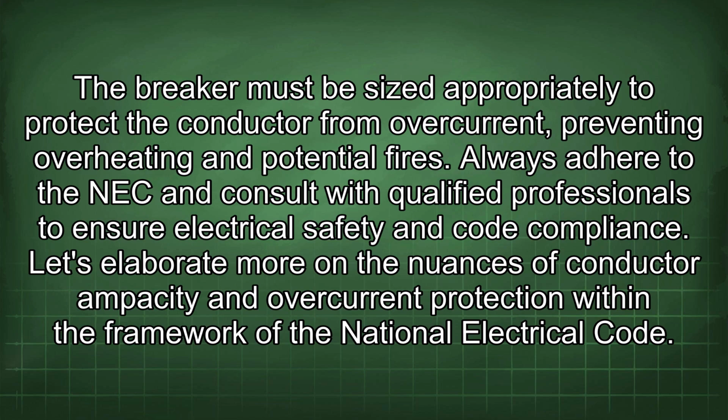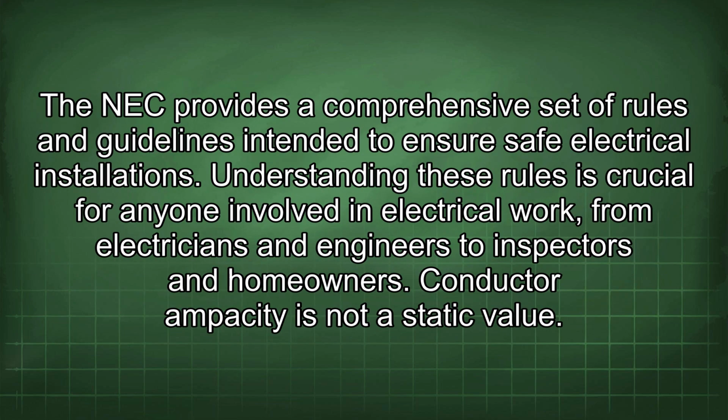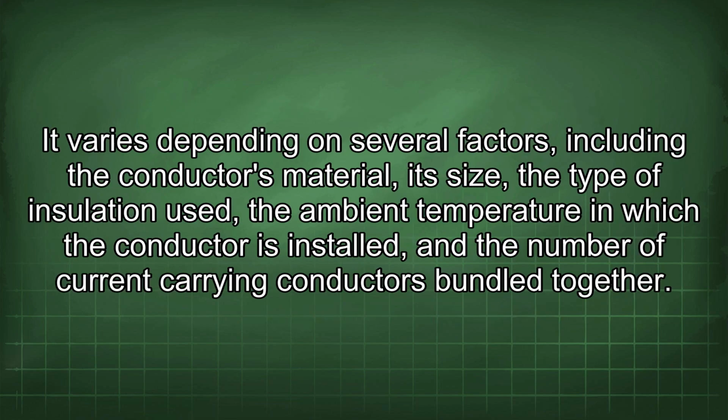Let's elaborate more on the nuances of conductor ampacity and overcurrent protection within the framework of the National Electrical Code. The NEC provides a comprehensive set of rules and guidelines intended to ensure safe electrical installations. Understanding these rules is crucial for anyone involved in electrical work, from electricians and engineers to inspectors and homeowners. Conductor ampacity is not a static value. It varies depending on several factors, including the conductor's material, its size, the type of insulation used, the ambient temperature